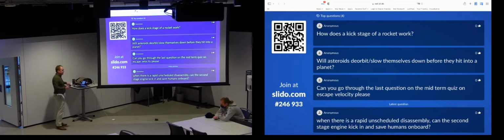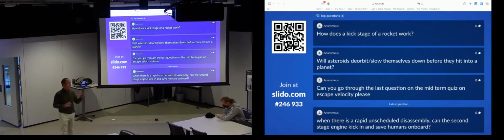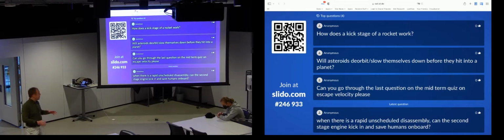Usually they're relatively small, but more and more commonly we'll actually use, say, our second or third stage for multiples of that. One of the most common orbits that we launch some satellites into is what's called geosynchronous transfer orbit. And so that upper stage kicks it into the transfer orbit, lets go of the satellite. Then there's usually motors on board the satellite, some of which can be discarded. Sometimes they're just kept for station keeping afterwards, that bring it into and circularize the orbit.